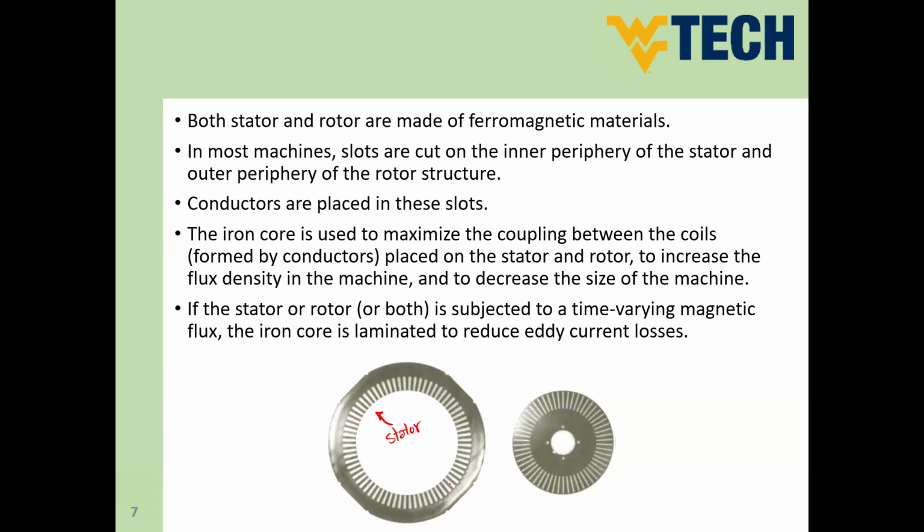And the inner part that we punched out from this structure will also have some slots like that. These are outer slots, but the others are inner slots. So inner slots in the stator to insert the windings of the stator. And here we have outer slots to insert the rotor windings. Okay. Here in the middle, we will have the space for our shaft. So here inside, this will be the shaft place.